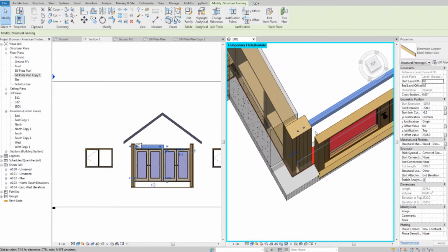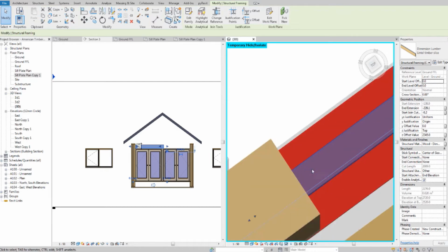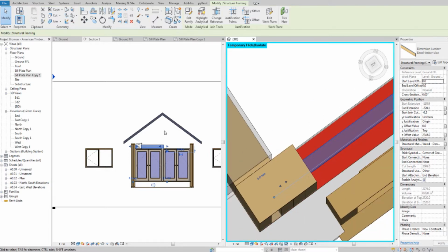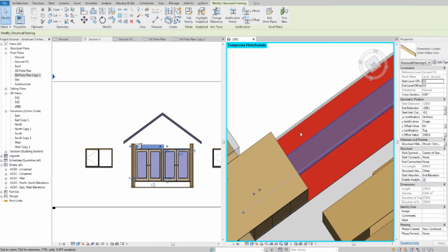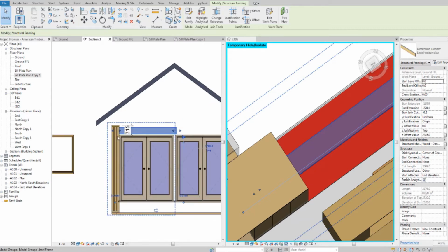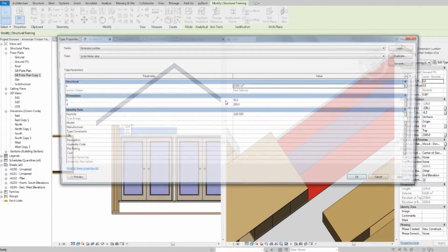So my plan for the lintel is to put a timber here, put a steel plate in the middle, which will be a 10mm thickness, and another timber here, sandwiching the steel plate in the middle. So if this gap is 150mm, 75, 75, 70, 70. So it'll be a 70mm thickness of the timbers and a 10mm plate in the middle. 70mm might be too thick and overkill, but it's okay. We're just modeling.